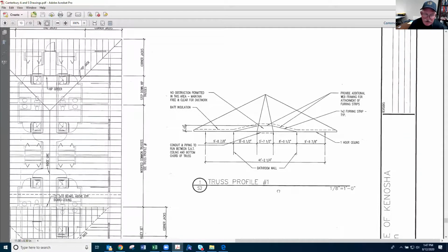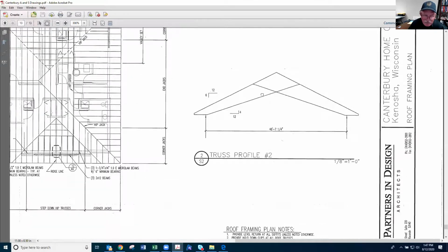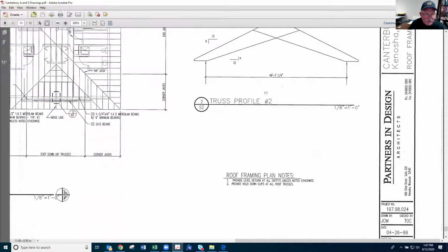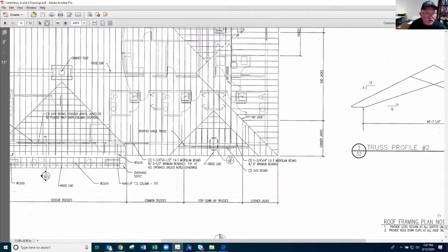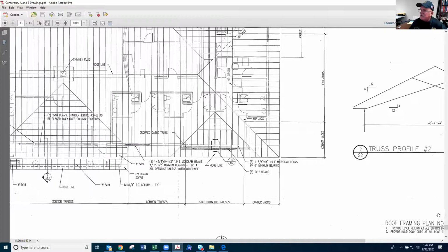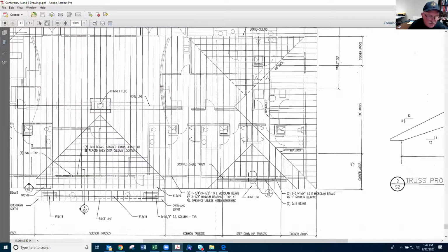But when you're looking at the detail on it, which they don't have a detail on it that they should on that ceiling, it should show that not only do the tiles have the rating, but so does the expansion between them. The metal pieces have to be rated along with that too. And we'll see it if it's in here. So we'll look at it and see.